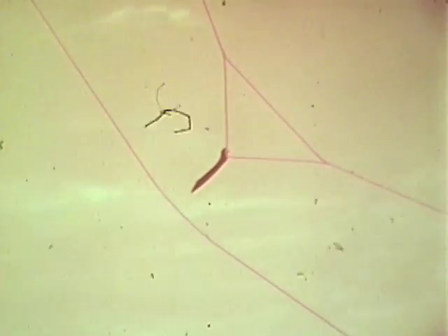Those bangs were shock waves from an aircraft in transonic flight. Let's see one of the ways in which they can be formed. As soon as the aircraft passes Mach 1, a bow wave appears. The aircraft pulls out of its dive and slows down below Mach 1, but the bow and tail waves travel on. They strike the ground where they are heard as...